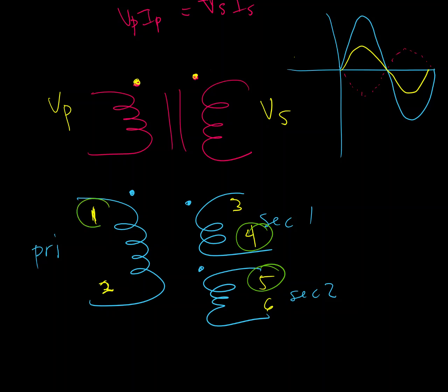Same if I wanted to measure resistance between 1 and 3, right? They're not connected either, so I should get an open circuit resistance reading there, or infinity ohms, however your meter displays that, because they're not actually touching. They're inductively coupled, but electrically they're isolated.